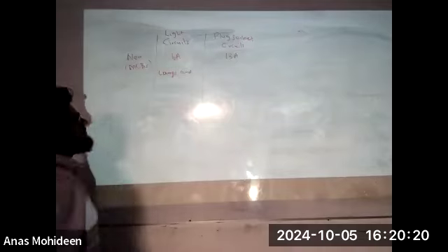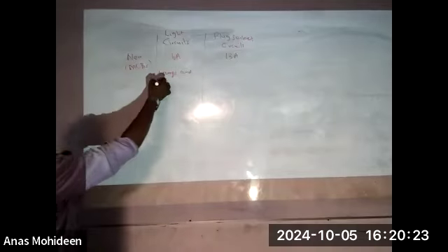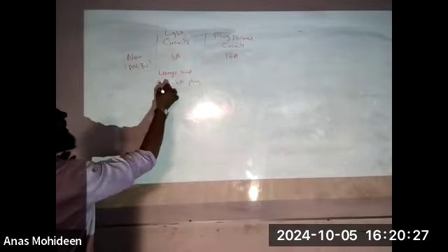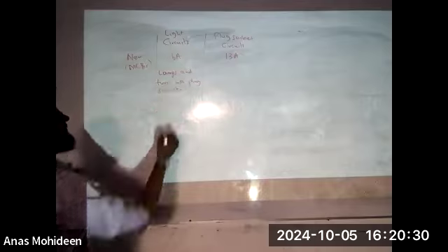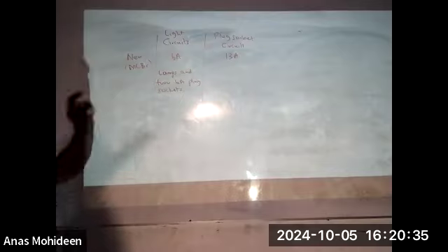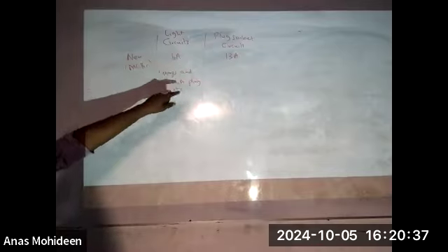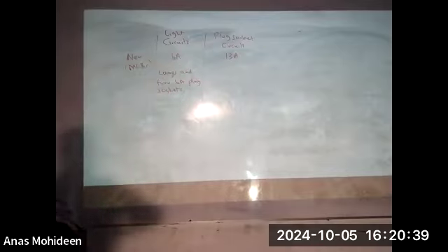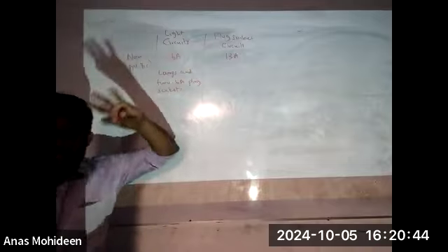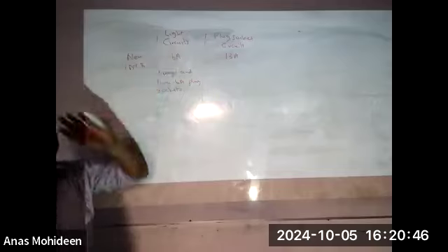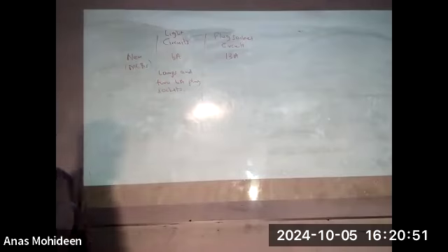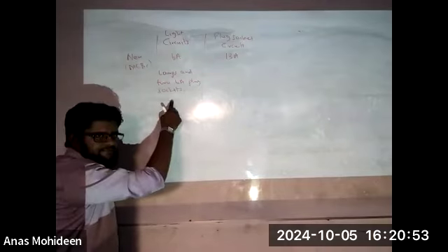And you see here, when you come to light circuits, guys, we can connect lamps and 2 plug sockets of 6 ampere. Look here, it comes in MCBs. A light circuit, lamps, is a common word given for all the connections: the lights, fans, everything. Any lamps, any switches you can connect over this light circuit. They have direct tapping, on off is given. Along with that, 2 plug sockets you can connect.